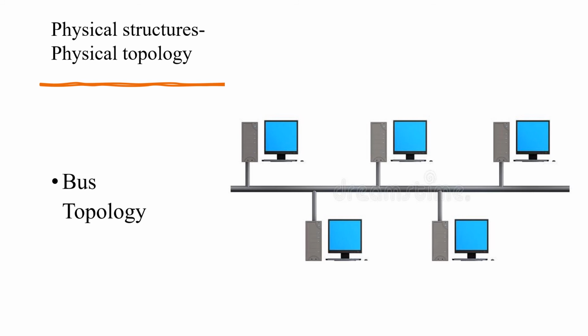Now the disadvantages include difficult reconnection and fault isolation. Bus is usually designed to be optimally efficient at installation. Thus, it is difficult to add a new device. Signal reflection at the taps can cause degradation in quality. A fault or a break in the bus cable stops all transmission, even between the devices on the same side of the problem. The damaged area reflects signals back in the direction of origin, creating noise in both directions.